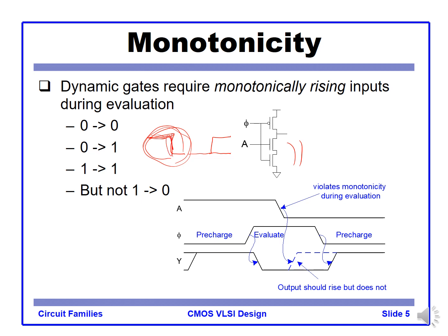For example, when the pre-charge happens, the output is charged high, and we start evaluation by asserting the clock. At that time the input is high, so it evaluates to the pull down, but somehow this input is wrong, so it adjusts to low. But there is no way to go up again because the pull down already happened. The pull up is not engaged, so no such operation is possible. So this output logic evaluation is wrong.